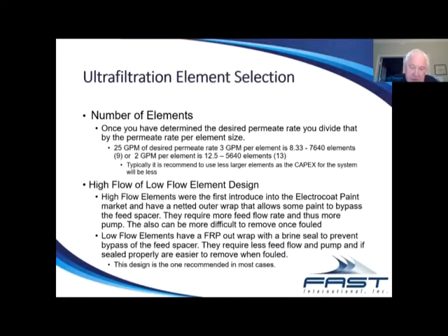The other criteria is, what do I do? Do I use a high flow or low flow element? I'd like to say for right now, most new systems are all using the low flow element. And it's somewhat contradictory, because a lot of people will think low flow means low permeate flow. And that's not really what it means. High flow or low flow is referencing the feed flow rate that is required per element.